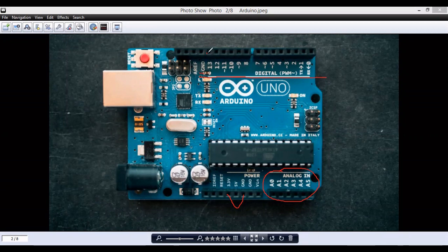So if you program the LED to be on pin number 13, then the ground is negative and pin number 13 becomes the positive terminal. If the LED has a negative and positive leg, you can just connect them both easily, and whatever program you wrote to make it fade, blink, or whatever, it will take place. This is obviously when the Arduino is connected to the board.